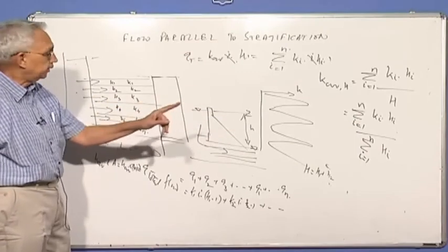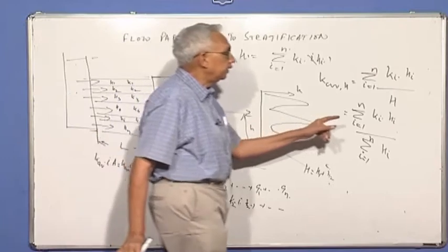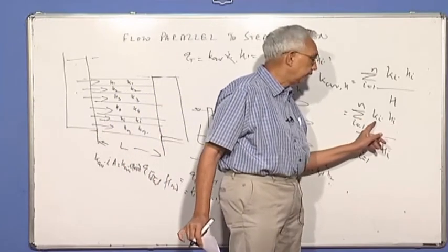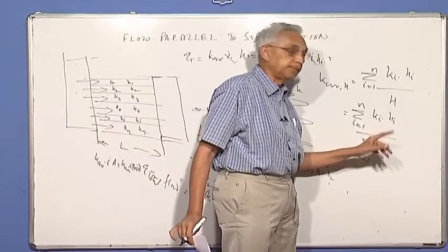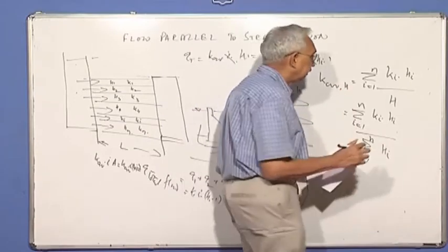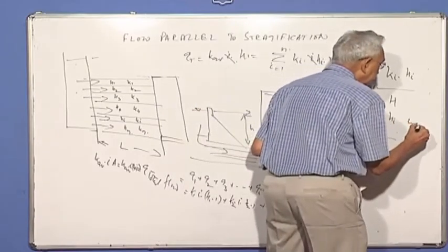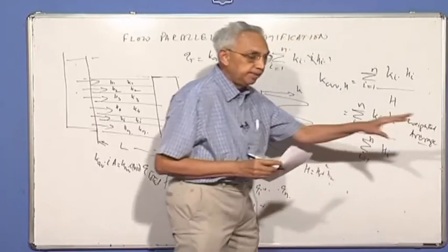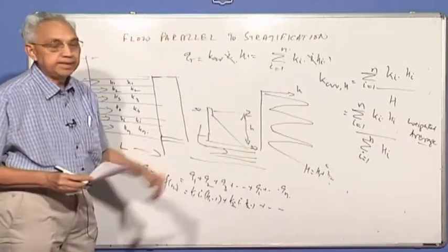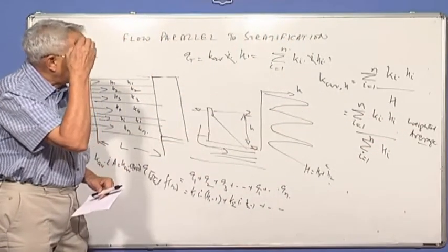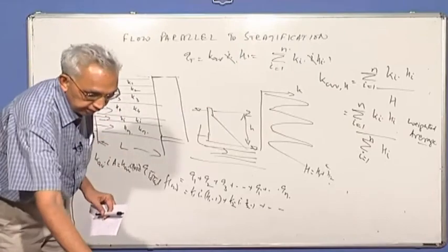What is the numerator? You are weighting, or adding, a product of coefficient of permeability times the thickness. We call this sometimes a weighted average. So for flow along the stratification, you can easily get the equivalent average permeability along the horizontal direction.